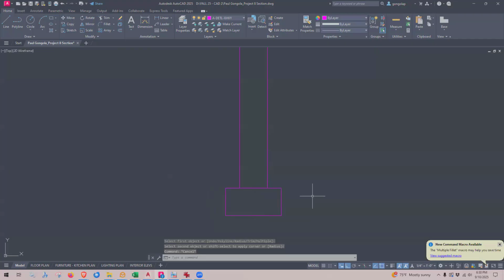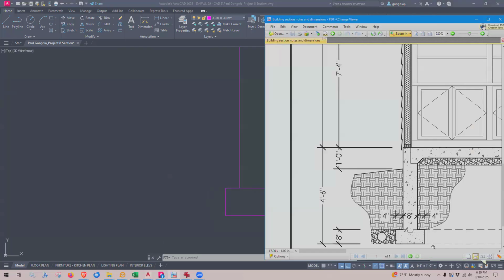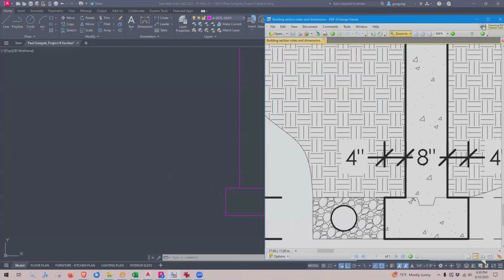Okay. So at the top of the footing here, you can see that this is the perimeter of the footing, and then there is a thin line here with a little notch, and that notch is called a keyway. So when the contractor is pouring the footing, he puts a little 2x4 in here, and then pours the footing and then rips out the 2x4 so that there is a notch here.